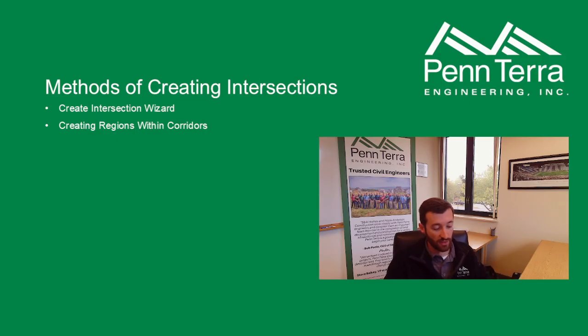So within Civil 3D, there are 2 main methods of creating intersections. There's a wizard to do it, which I'll show a little bit, and then there's also a method of creating regions within corridors to do basically the same thing. A couple notes. The wizard walks you through. It uses a system of dialog boxes. It's very step-by-step. It tends to take a little bit of time, but it's very thorough.